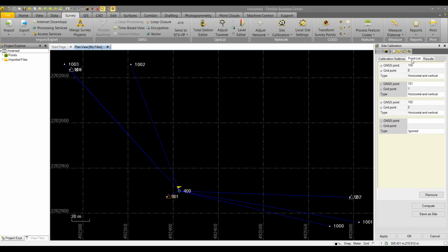When you get to 3 points, and you're doing a horizontal calibration with 3 points, it's a lot better. Now you can actually have a check on the 2 other points you held previously. And I'd say when you're doing horizontal, you probably want to use at least 4 as a minimum. Obviously, I'm breaking that rule in this job right away. We only had 3 points, so sometimes you do have to live with it.